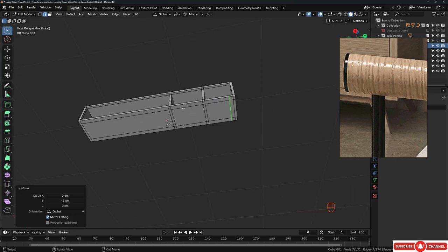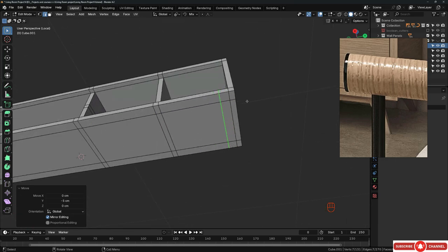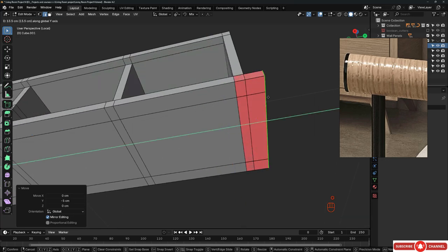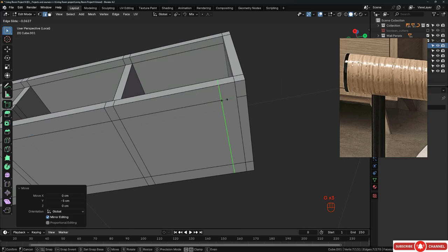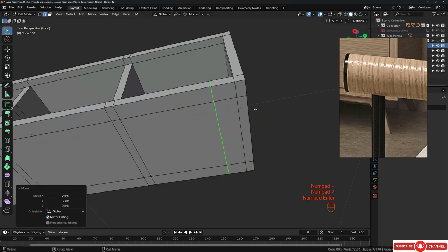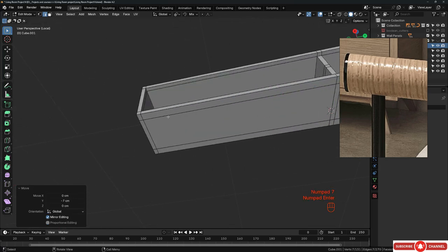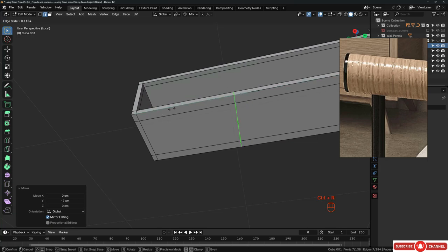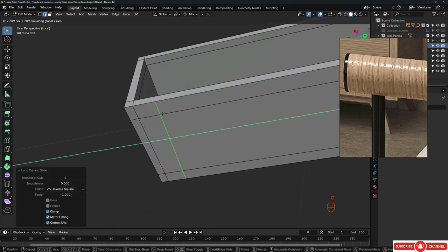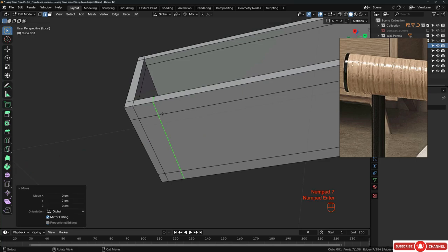And if I want to get something similar on that side, I should do the same. But let's make sure that this distance is really what we want. Maybe we should go beyond 5. I will hit G twice and slide it and stop it right here, and I will hit G and move this back to almost 7 minus. Alright, I should do the same here. Hit Control R, add one edge and push it on this side, and then hit G and go to 7 centimeter here.